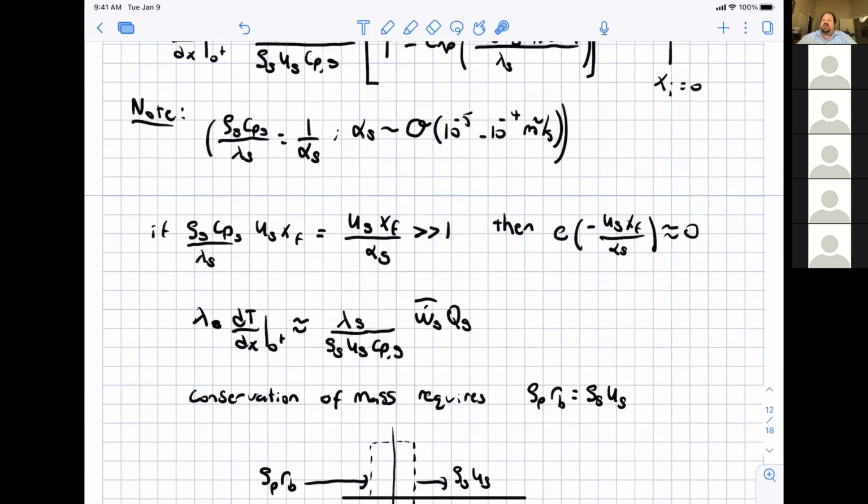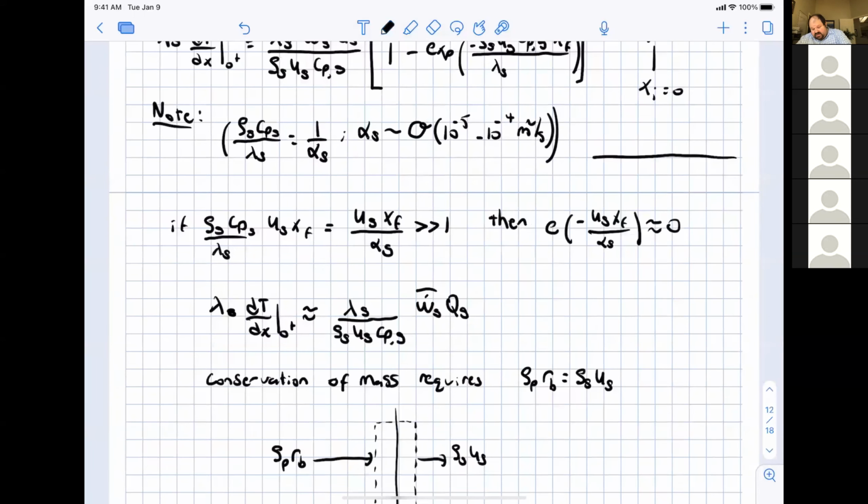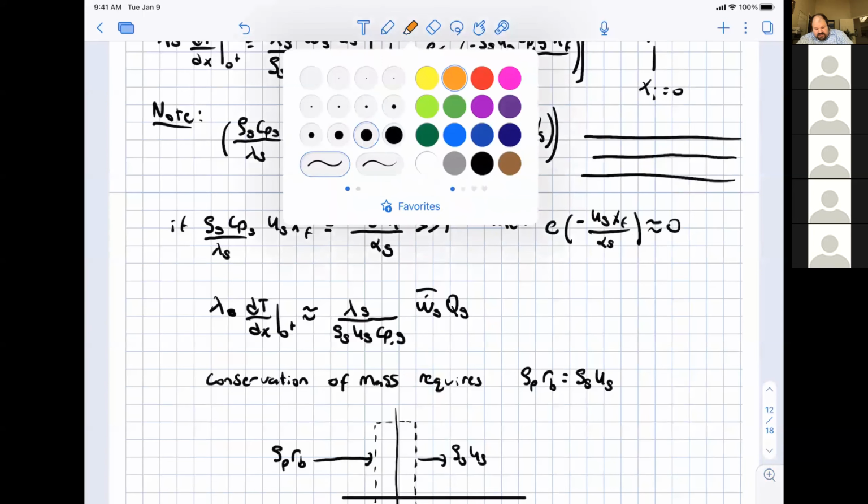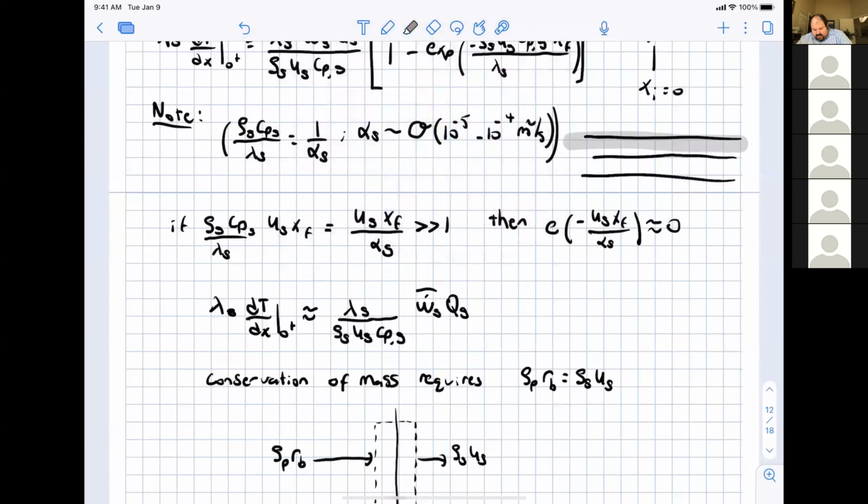that's also why in a lot of rockets, behind the propellant itself, you have the propellant here, and then the combustion chamber, there usually is not very much insulation. If this is the outer wall of the rocket, and this here is the propellant, there is not that much insulation normally between the propellant grain and the outer casing of the rocket in a region where there is propellant.